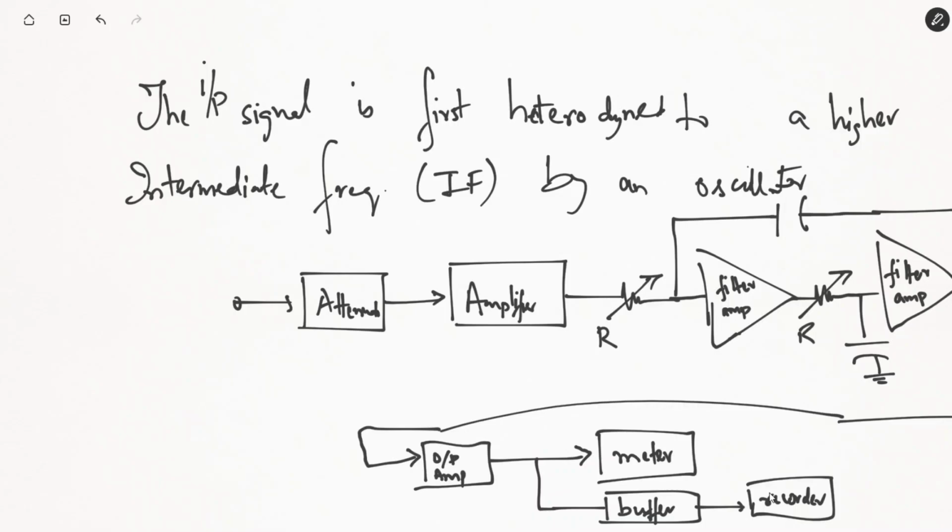So the output of this heterodyne system will be the IF range that I told you, and once we are tuned to this particular workable range, we can feed it to the filter and select a particular frequency component. After filtration, this will be a band pass filter.